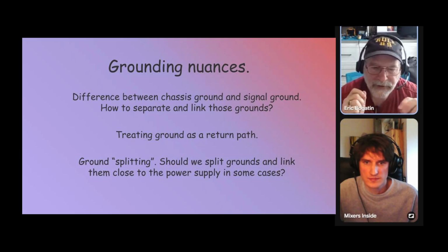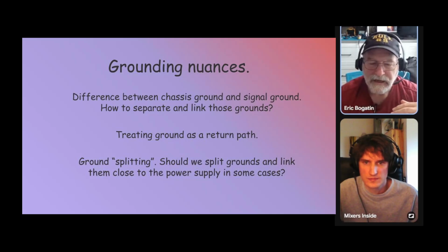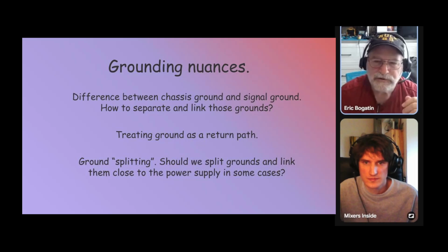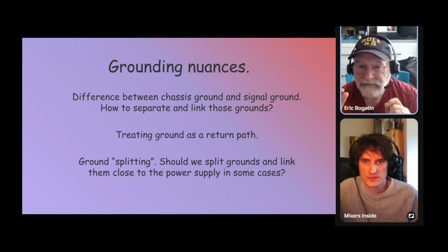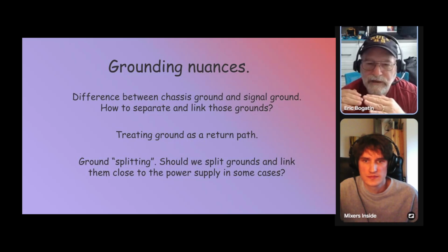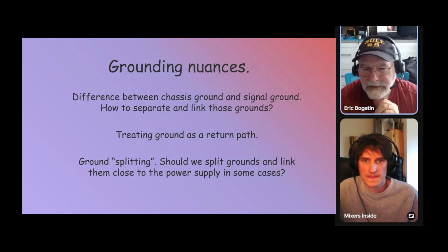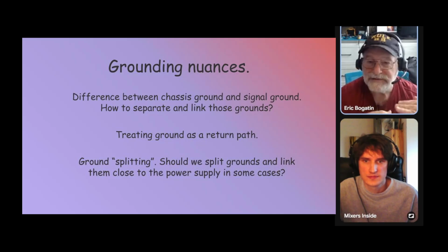If we used a path from the local ground of the microphone onto the circuit board ground plane, and there was current in that ground plane, and that current is modulated by 60 hertz, or by power line noise, or by return current noise, then we're going to see that noise at the input of the amplifier on top of the microphone input. So thinking about the interconnects in terms of reference ground and return current helps to identify where the source of the noise comes from. And I find it very useful in looking at any low-level signal, regardless of where it is.